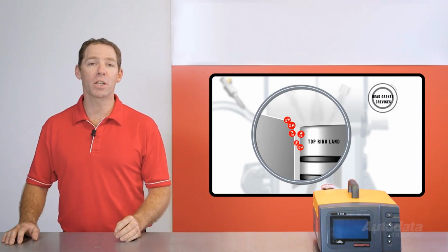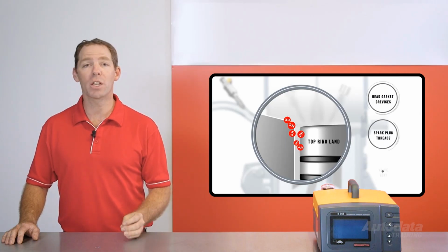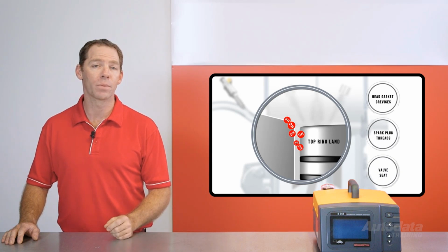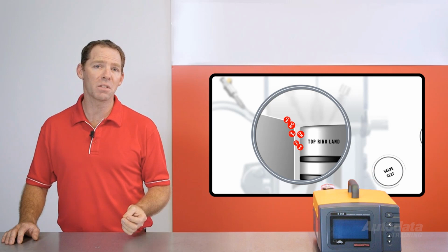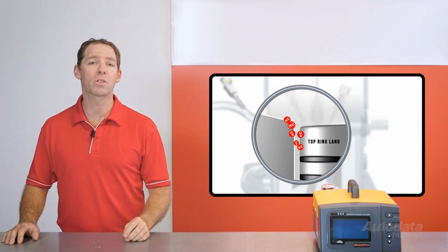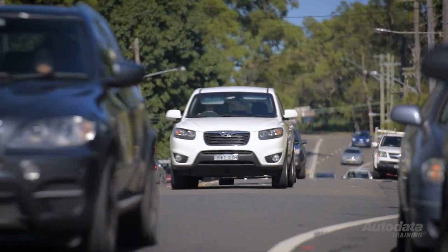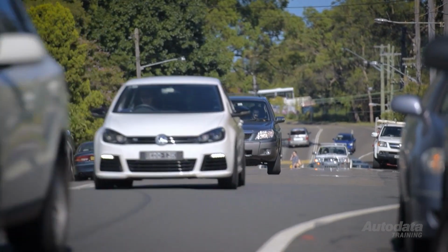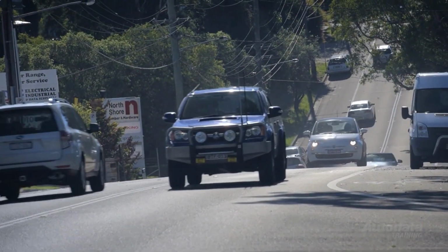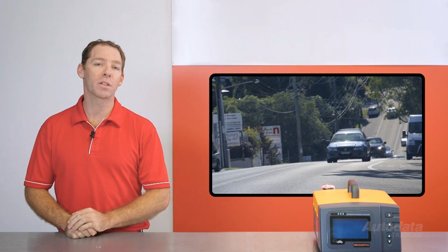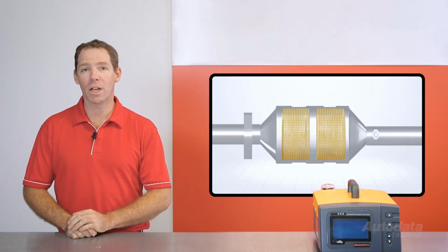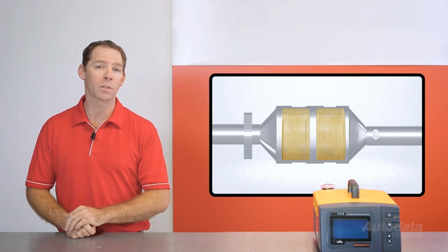All internal combustion engines produce some percentage of hydrocarbon emissions. Manufacturers try to limit this amount with efficient cylinder head, combustion chamber and piston designs. To control the escaping hydrocarbon emissions, manufacturers employ exhaust after-treatment devices and systems that further reduce or convert them. In most cases in a gasoline engine, tailpipe hydrocarbons are controlled by an exhaust catalyst.